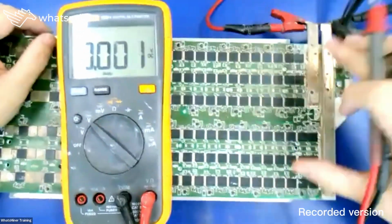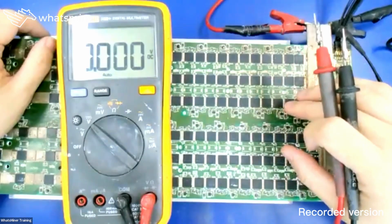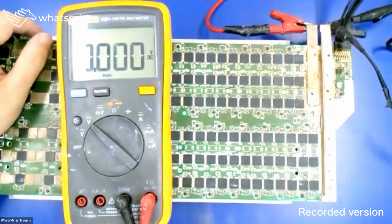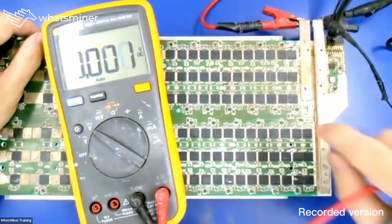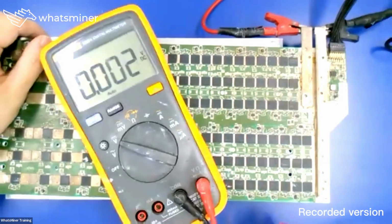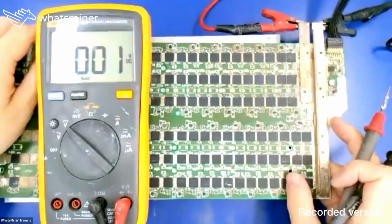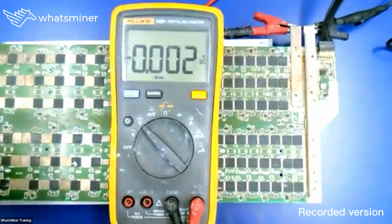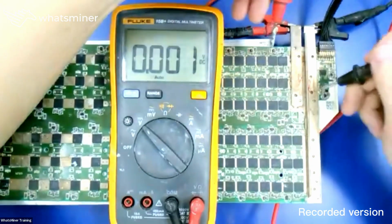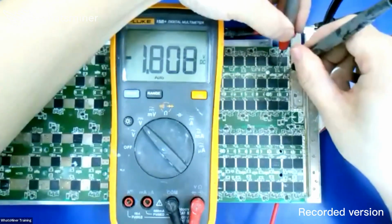We know when you power on, the initial state of RxD and TXD on the board is over 1.8 volt. So on a normal board, when you power on, RxD is transmitted from the first chip to the last one. So at the last chip on a normal board, the RxD is 1.8 volt. So measure the RxD at the last chip. Now it is 1.8 volt.